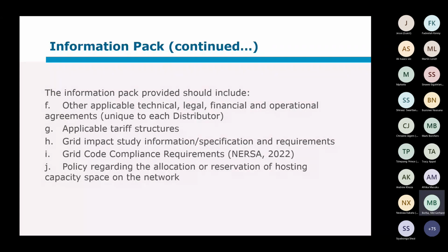All right, so hosting capacity, let's say the 10 megawatt transformer. Let's say you do not go up to full capacity on your transformer. Let's say 80% loading, and you've already got a 5 megawatt generator there. It means you can connect another 3. If you have a 3 megawatt application, but that customer is only early in the stages, you're not going to allocate that necessarily, even if you apply it first.